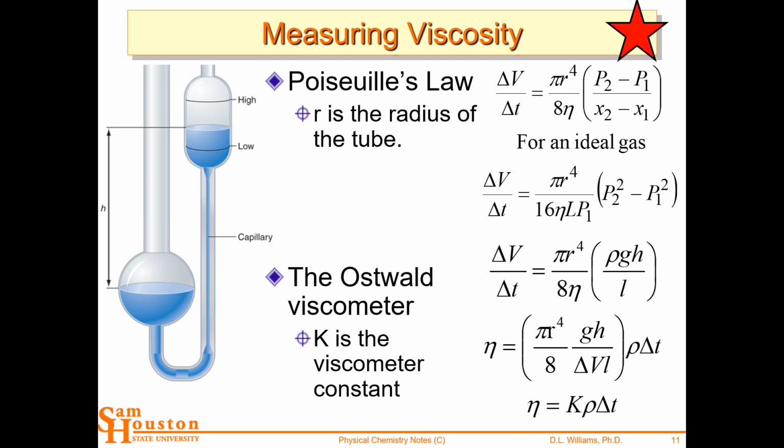Okay. If you change the pressure, so we have pressure in here. Pressure is in the numerator, and it's pressure difference. So if you have 1,000 psi at the beginning and 1 atmosphere at the end, so that's 1,000 atmospheres or 1 atmosphere, then you have 999 atmospheres difference in terms of the pressure head. And so that's, again, if you double the pressure, you double the flow. Okay. If you double the length of the pipe, you'd cut the flow in half. Okay. If you double gravity, you double the flow.